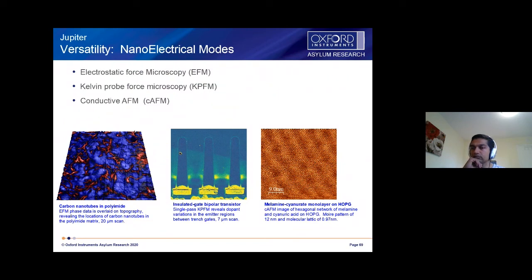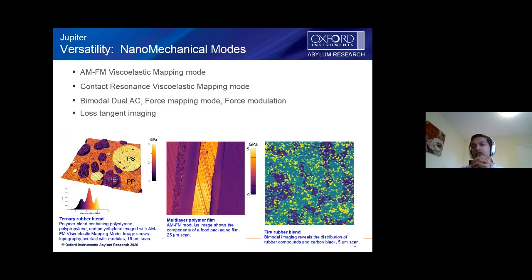Excellent. Is this equipment capable of measuring mechanical properties of thin film, specifically nano indentation of films of 100 to 500 nm films? Yes. The instrument has a measurement mode called force mapping. Depending on the amount of force that you want to apply on your films to measure their mechanical properties, the instrument is capable of performing indentation experiments.